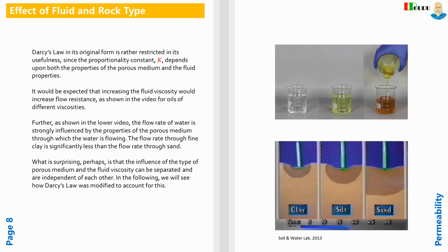The flow rate through fine clay is significantly less than the flow rate through sand. What is surprising, perhaps, is that the influence of the type of porous medium and the fluid viscosity can be separated and are independent of each other. In the following, we will see how Darcy's law was modified to account for this.